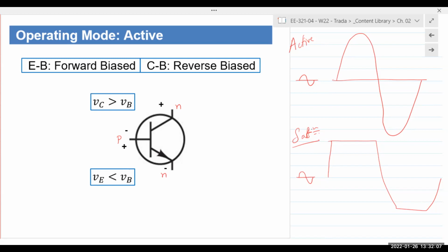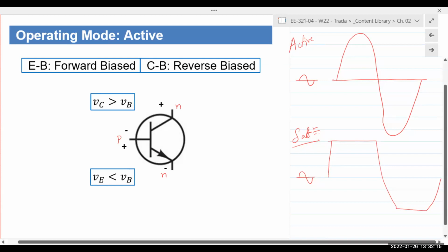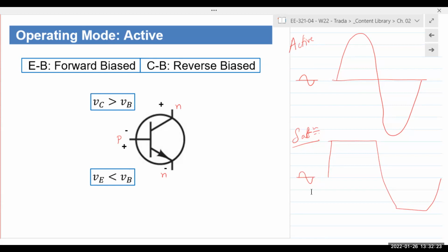It's amplifying so much that the top limit is just getting cut off. And if it's even more amplification, then the output is just like a flat line. Instead of time-varying signals, you just see a flat line. This level comes from the DC voltage that we're applying, right?